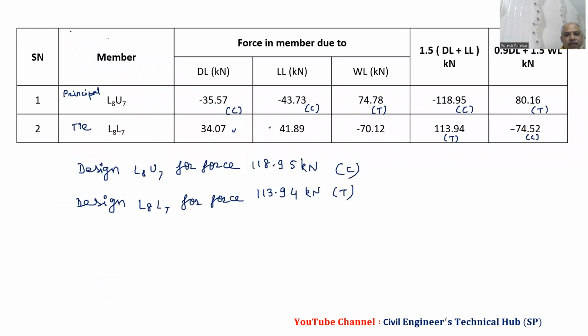Now we will go with another member. Now you can see we have this as first member. Second member L8L7. That is 113.94 tension. So member L7L8 or L8L7. So we have to design for 113.94 kilonewton tensile.